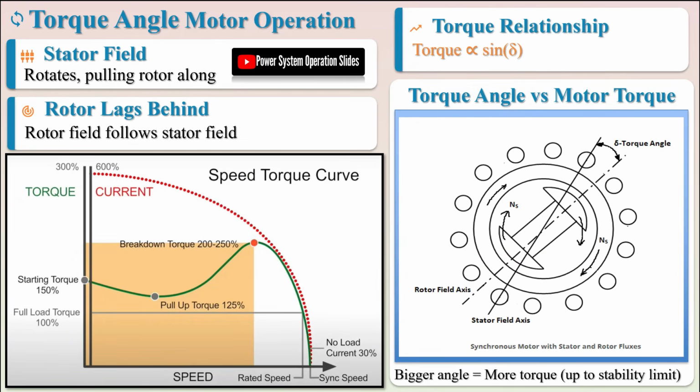Active power naturally flows from the node with the higher power angle to the node with the lower power angle, much like water flowing downhill due to gravitational potential difference. This angular separation acts as an electrical potential gradient for active power, telling the megawatts where to go.